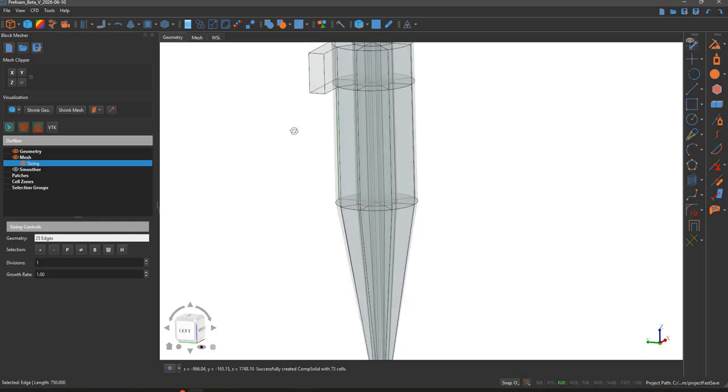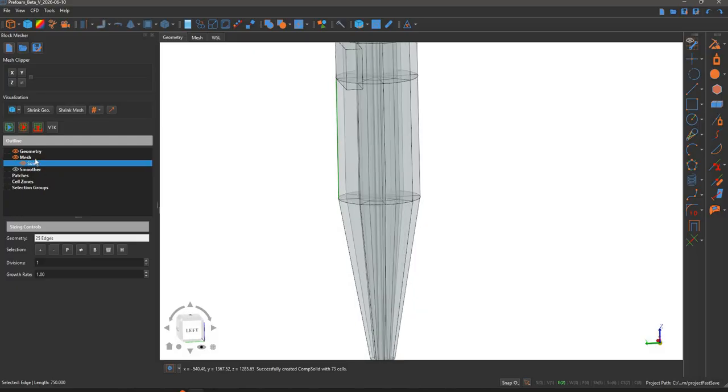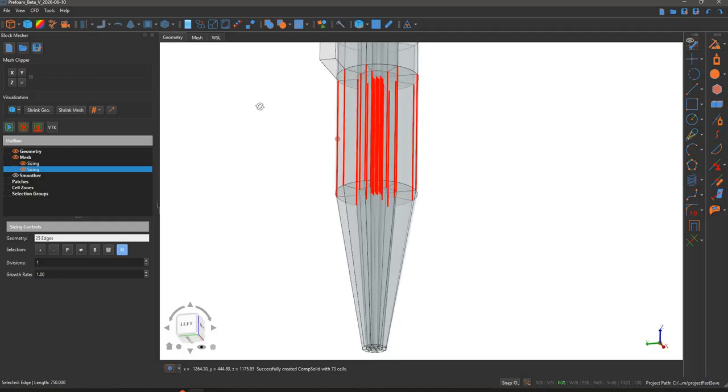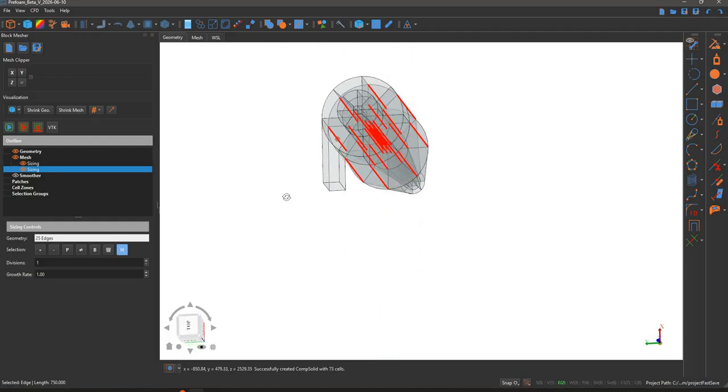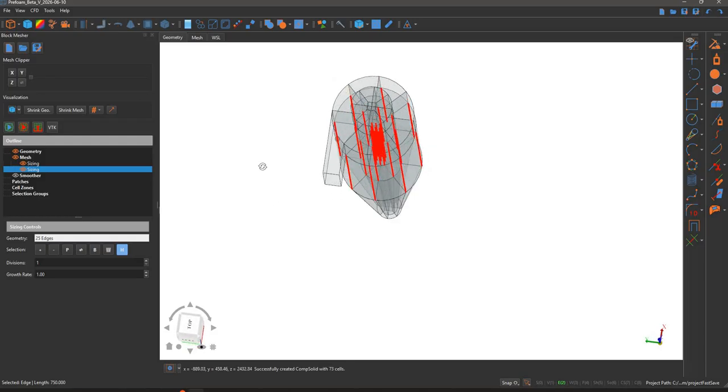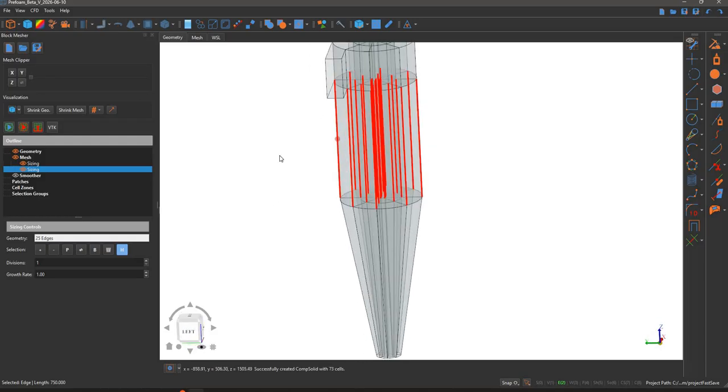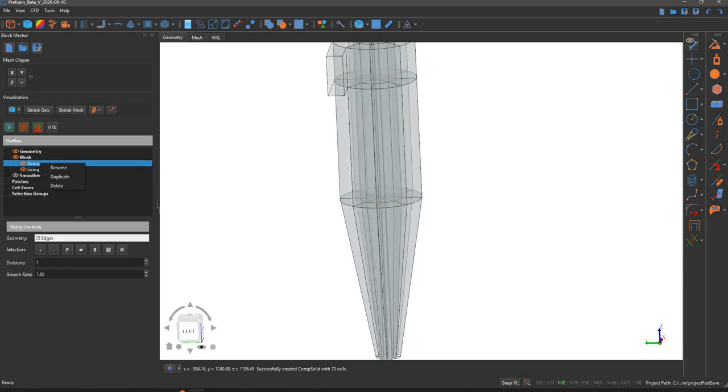Next thing is on the cylindrical sections, you can also select one. Create new sizing, add it, and then propagate, then highlight. You will see all the contradicting edges will be grouped together. So that will prevent you from creating contradicting values. You can also rename this like bottom vertical, and this like midsection vertical.